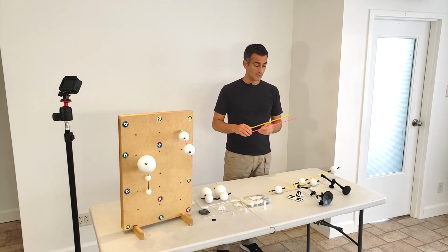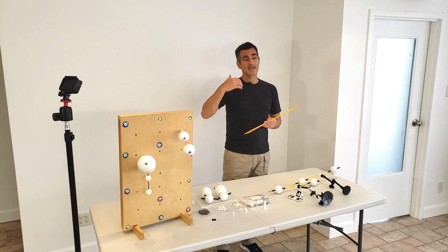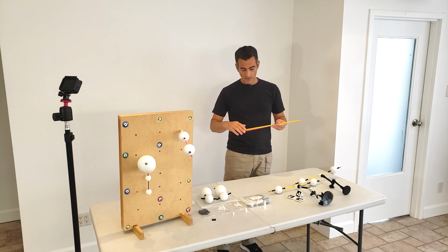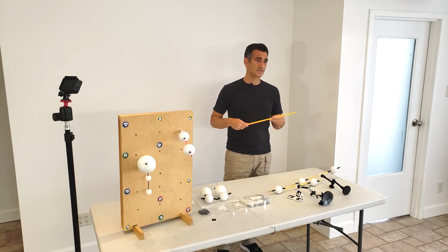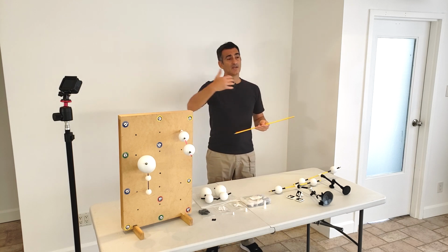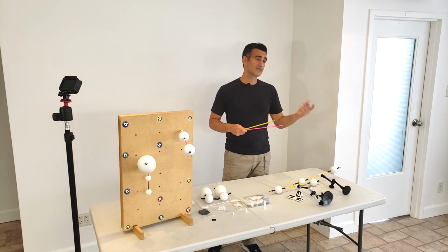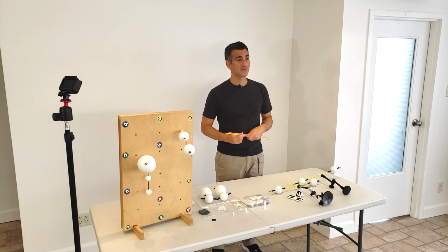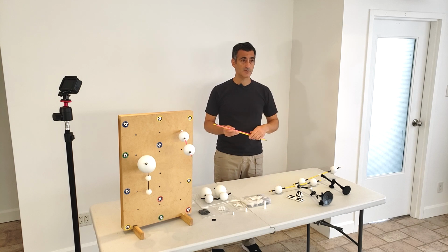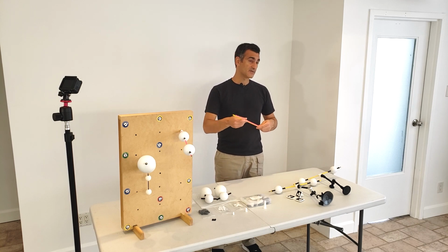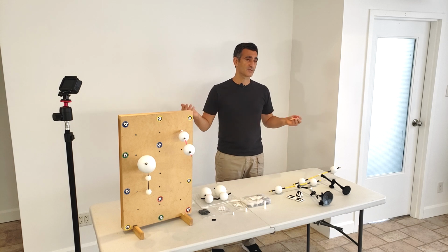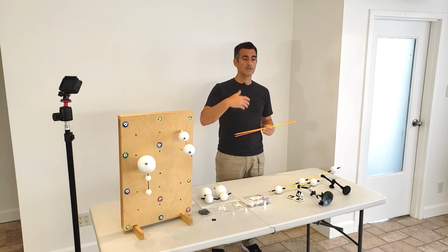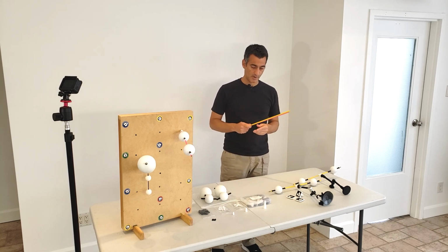The way to correct for that is to scan at a very high resolution when just using a rod. That's really important. So scan at a high resolution and not be far, far away. Many scanners give you the ability to move farther away, focus in on a little window, and then scan at high resolution, which is one way you can recover some points. But of course there's always a limit. You can't be 50 meters away and expect to get these rods up close. If you can be close and scan the rods, no problem.